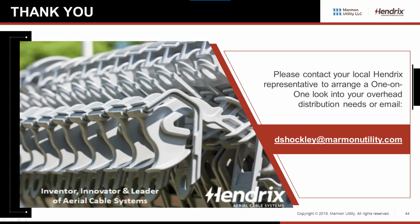The other places, even on transition points where you've got covered conductor on one side of the pole and bare conductor on the other, we like to see a set of lightning arresters there. With regards to the messenger, our recommendation is we don't want clients to go any more than 500 feet without grounding the messenger. Most utilities I've worked with ground it at every pole. So it becomes a pretty well lightning-protected system, believe it or not.